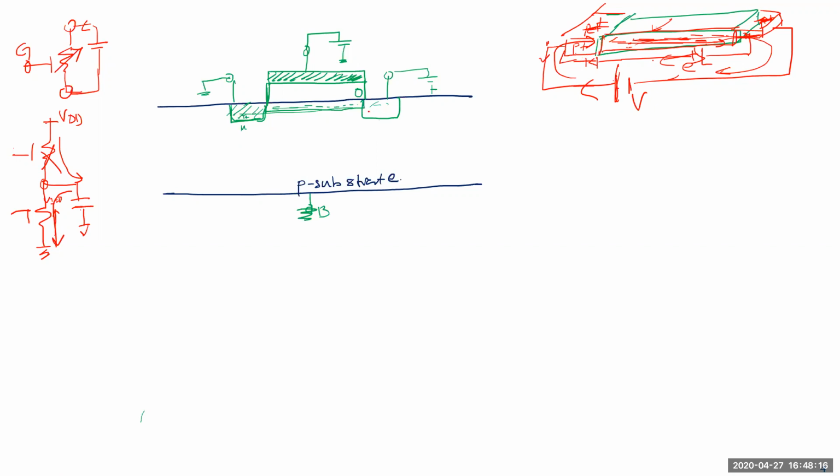If you put metal here, you can conduct it, but you just can't fabricate it. The fabrication is not possible in metal, and it has other problems too, like stress and melting and all that stuff. So it's a fabrication issue. You can put a metal and conduct. And there is another thing, what's called a Schottky diode. Once you put a metal, there'll be a Schottky diode here, here, and here, and that also will have a huge problem on how you create that channel. But if you ask me just an isolated channel with the metal plus, yes, it'll work.